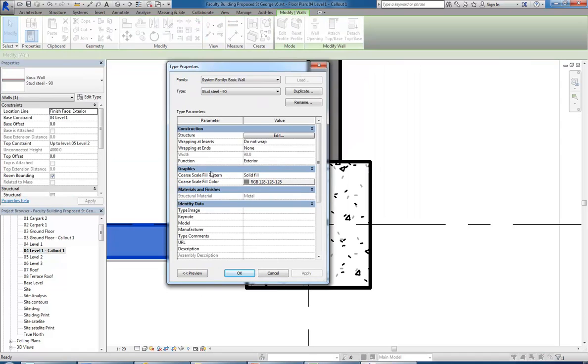So you've got this graphics section for things like walls and floors. Would you have an idea which objects give you that coarse option? It's a certain type of object, getting into the technical side of Revit, but it's good to know. Hopefully you've been thinking a little about those family types I mentioned at the beginning. You've got system families, and then all the others, loadable families and model in place. They're the two basic kinds of objects you've got in Revit.